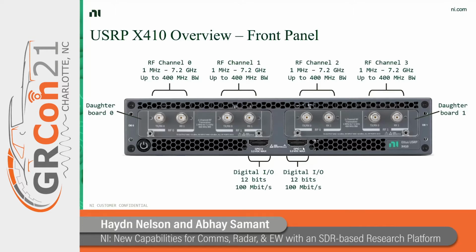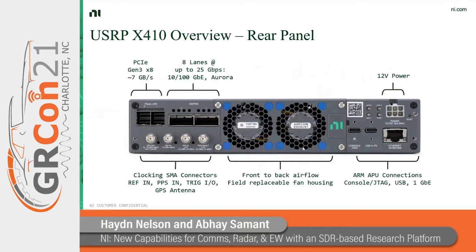You can do some level of phase alignment here with some digital controls of the VCOs and local oscillators internally, but there is no local oscillator import and export. But it does have 4 channels in and 4 channels out. And you can take a look on the back. It does have timing alignment capability with a 1 PPS and a 10 megahertz clock. So you can do time-aligned operation with this radio using a GPSDO on board.